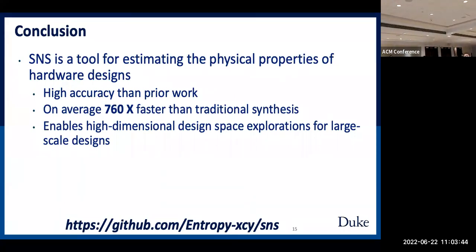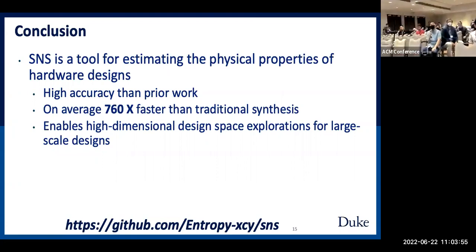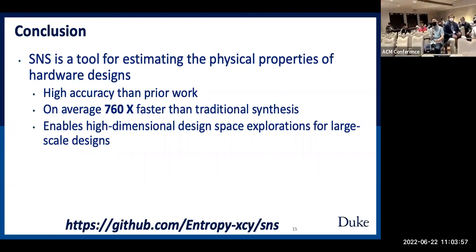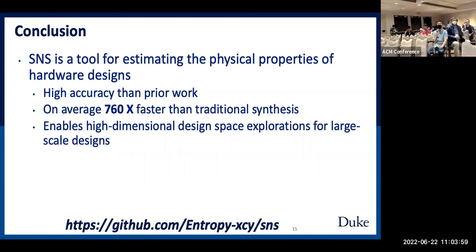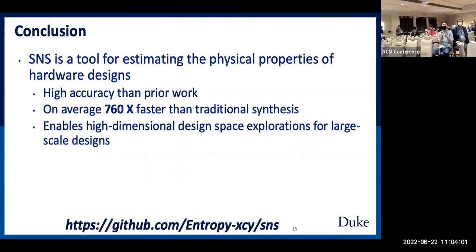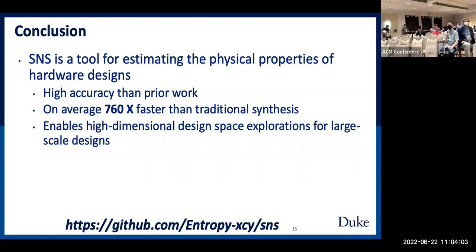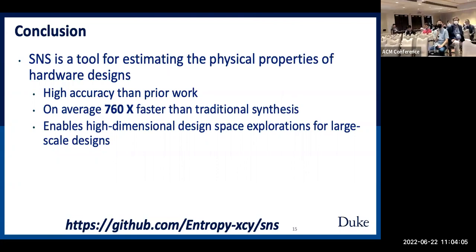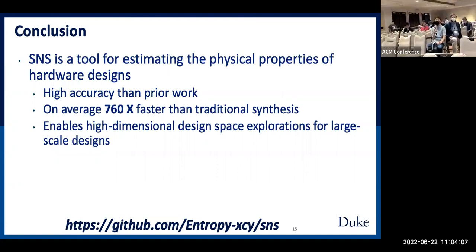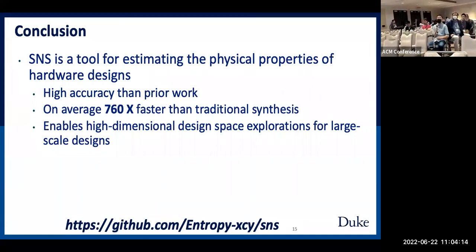It's an amazing work. One thing I am a bit confused about is, in one of your examples, when you said how you extract the paths from the netlist, in some cases, one cell might be counted in multiple paths. For example, in the MOADD case, the adder and the multiplier are counted multiple times. And for each of these paths, you assign a power to them. So when you are summing up these paths together, aren't you recounting the power for each cell many times?